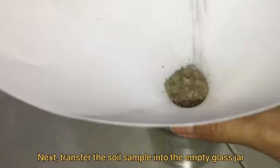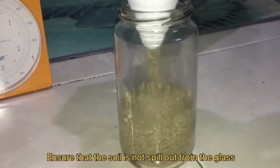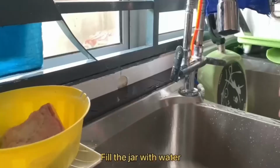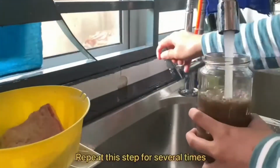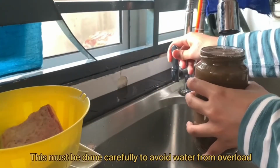Next, transfer the soil sample into the empty glass jar. Ensure that the soil is not spilled out from the glass. The glass filled with soil is then weighed and recorded as M2. Fill the jar with water and then shake it. Repeat this step several times. This must be done carefully to avoid water from overflowing.